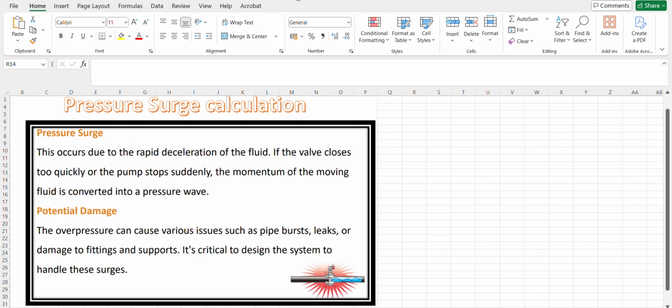So we will see how to calculate the max pressure rise, and based on that, if that falls in the case of high surge pressure, then the design pressure of the connected system, or that may be piping, has to be checked. So the necessary mitigation measures or preventive actions are to be taken based on that. That is the latter part, but first we have to come to what would be the max pressure due to sudden change in velocity due to rapid closing of valves and all these things.